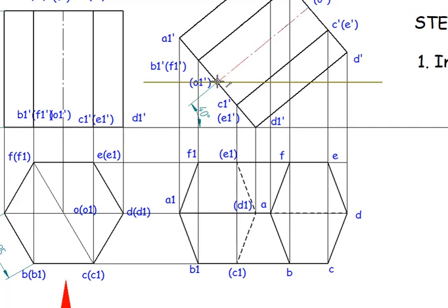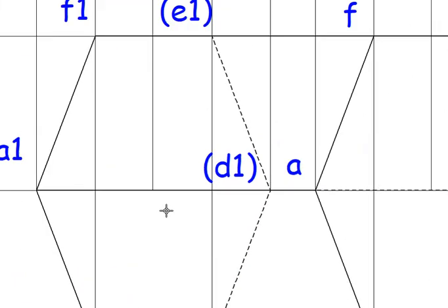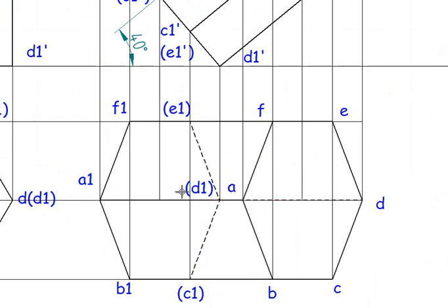From here till this point, from here till here. Axis line is a thin line of 0.13 thickness, and hidden line is the dash type line, but it is going to be 0.5 thickness. So from here till here axis line is there, but we cannot represent the axis lines. So instead we can just represent the annotations here.